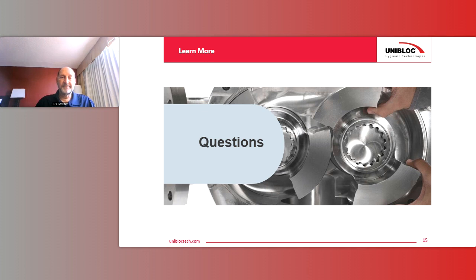Sounds good. The next question says, how can an AODD pump only have one nut? Okay, so as the slide showed there, it's due to the design of the pump itself. It's an inside-out design. So by taking that different take on the mechanical attachment of the pump, it has a center shaft that then can allow one nut to hold the whole pump together. So it's just in the unique design of the way it was done to be able to hold that together with one nut.